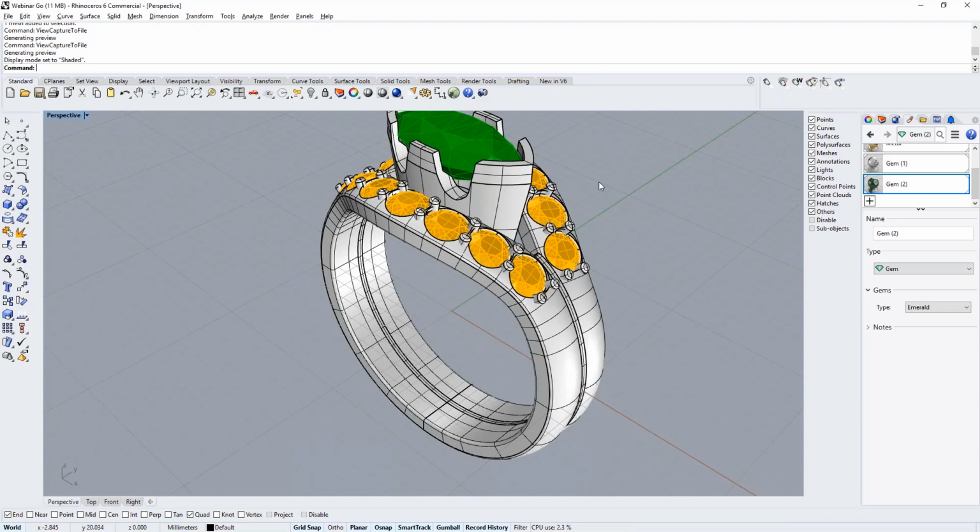I think she may be referring to offset. Okay. And it depends entirely on the scale of the gem. Yes, she agrees. That's what she was asking. Right. 0.4 millimeters is about the minimum. On tiny little round bezels, sometimes you can successfully print and cast maybe down to 0.3, but 0.4 millimeters is a great standard.